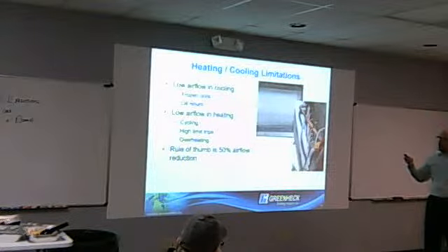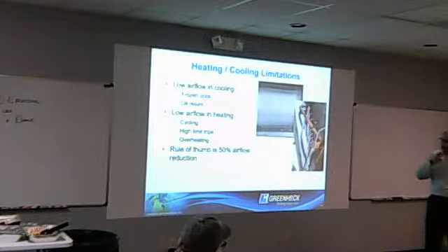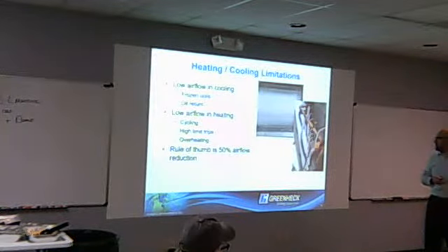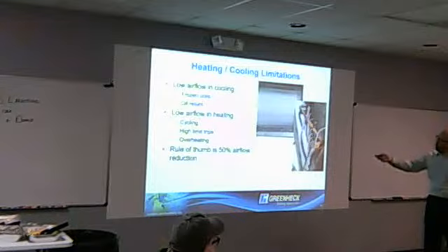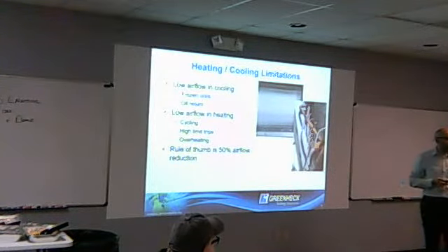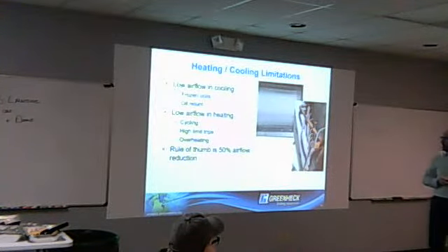On the cooling side, you're familiar with what happens with low airflow across coils, like you mentioned earlier, Terry, about oil. Low heating, the cycling, the high limit trips, overheating. We don't want the condition where the heat exchangers burn in there and there's no airflow over them. And as a rule of thumb, that 50% I referenced keeps you safe, but you could go low.